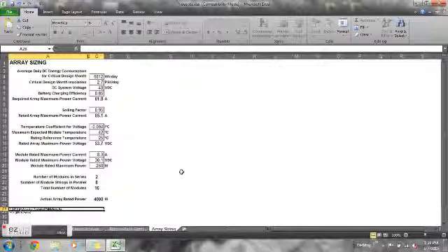Now that we have our battery bank sized and ready to go, it's time to start sizing our array. The array must be sized to produce enough energy to meet the load requirements during the critical design month while accounting for normal system losses. This ensures that batteries will always be charged and system availability will be high throughout the year.